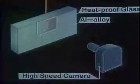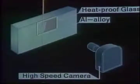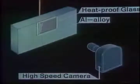A block of aluminium alloy is in contact with heat-proof glass. An electron beam is impinged a little inside of the metal along the metal and glass boundary plane. The beam hole front is at the left end of the bright part, where it is clearly seen that a bright point is flowing downward. This fact means that the front wall is melted not uniformly but locally, and such a melting zone moves with time.